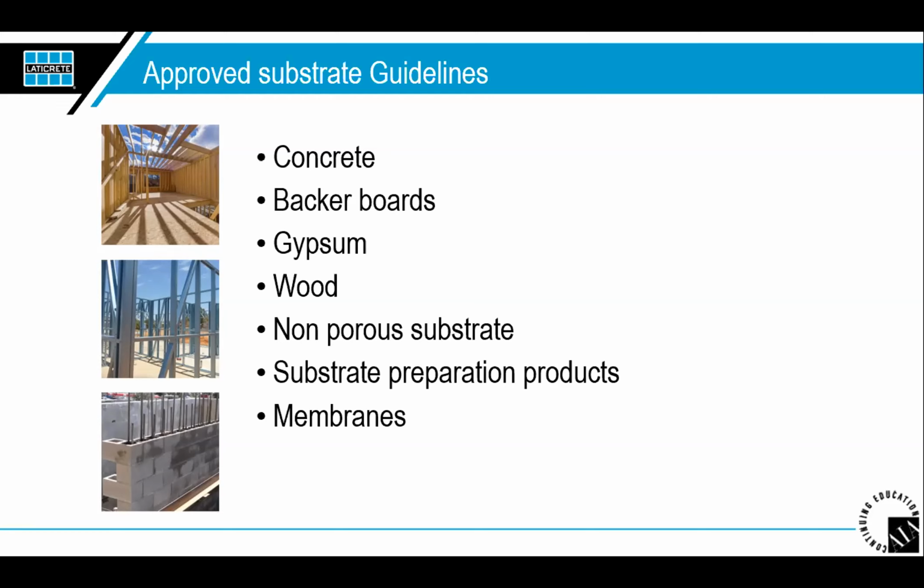We get the question quite often on my side of the fence: hey, we've got metal to go over in an elevator. We have metal stair treads. We have terrazzo that we don't want to tear up because of the cost factor there. Can we go over top of it? We can. The installation materials have come so far that we can actually get right on top of that. We may have to use different liquid applied membranes, but we can do that.